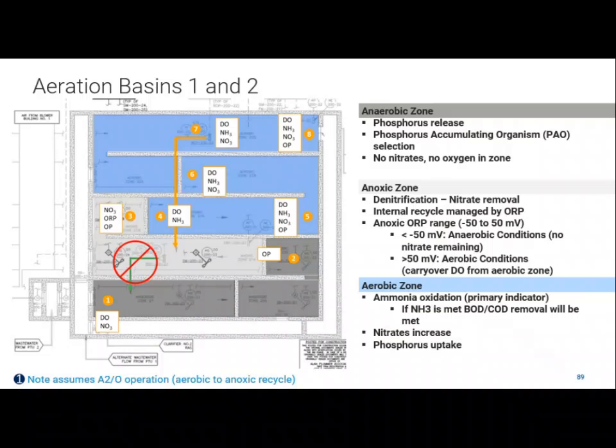I say that just as you start to see other BNR configurations, you're like, oh my gosh, 15 mgd, I've got to pump that much. You do, but it's very low horsepower. That's probably only like a 20 horsepower pump. It's not a massive pump.